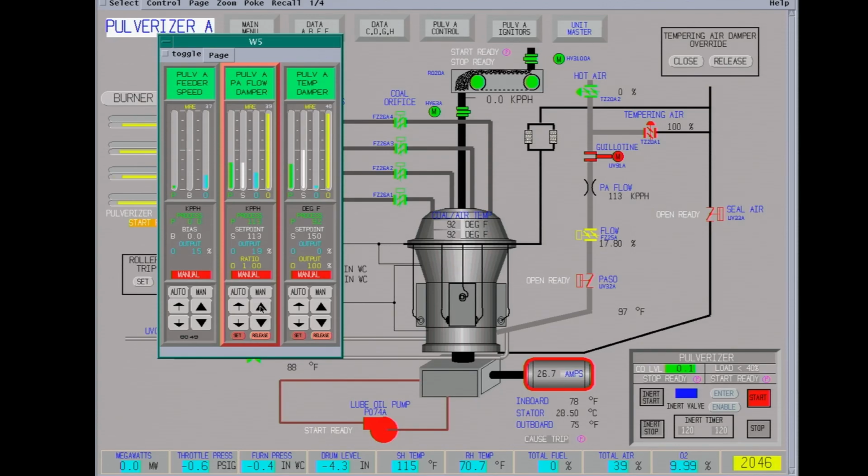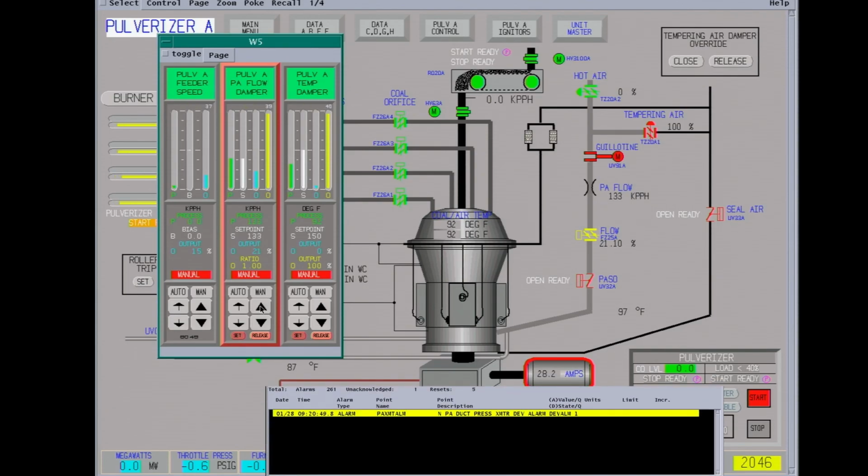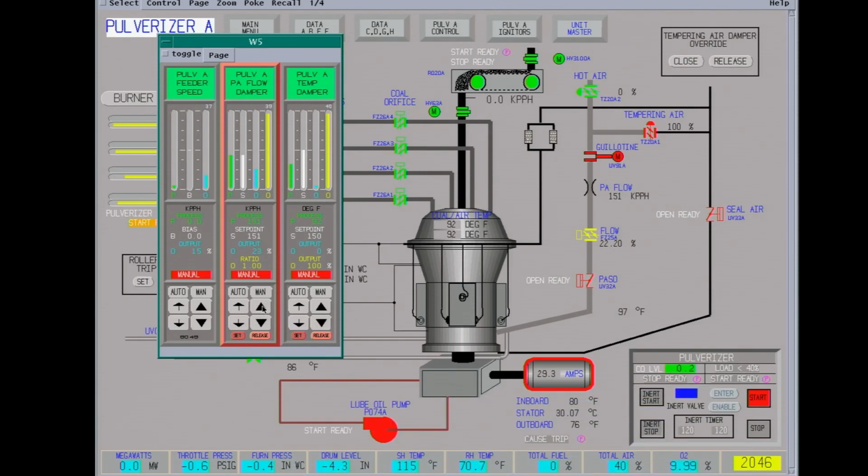These pulverizers usually will leave the classifiers alone on top. They help with the coal fineness. We have two older style pulverizers where you have to adjust the classifiers from startup to running. But this newer style seems to do a pretty good job. You don't want big pieces of coal blowing in. Yeah, it cuts down the efficiency.